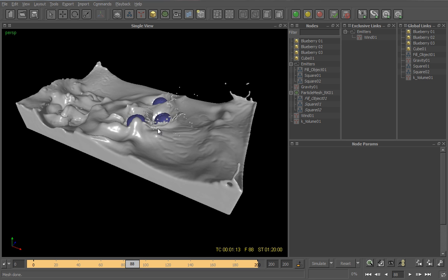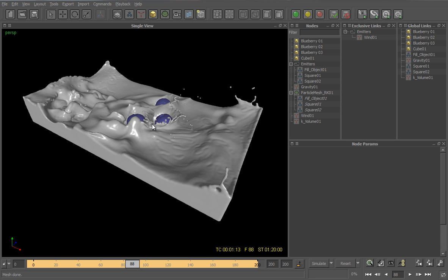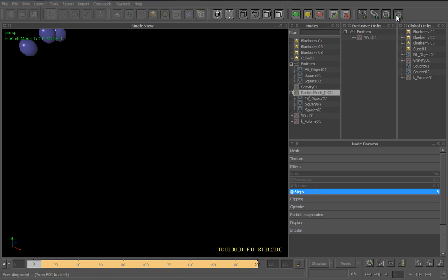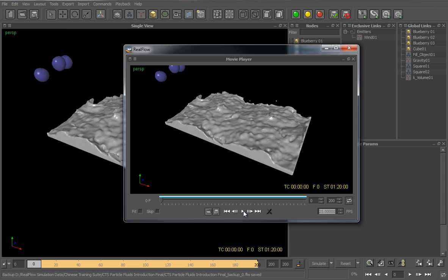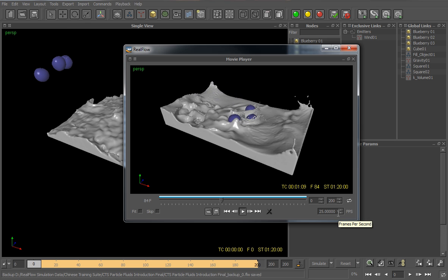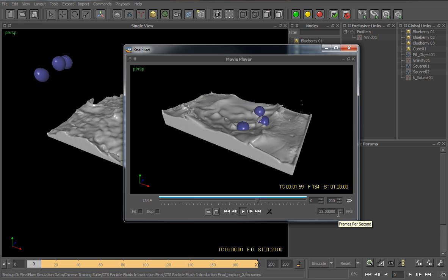Now, the mesh fulfills our expectations and we can try the settings with a few more frames. When the results are satisfying, the entire mesh range can be created. Rewind the timeline slider and click on the Create Mesh button. Once RealFlow has finished its task, you should create a new preview, evaluate the mesh, or import it to your 3D program and render it.